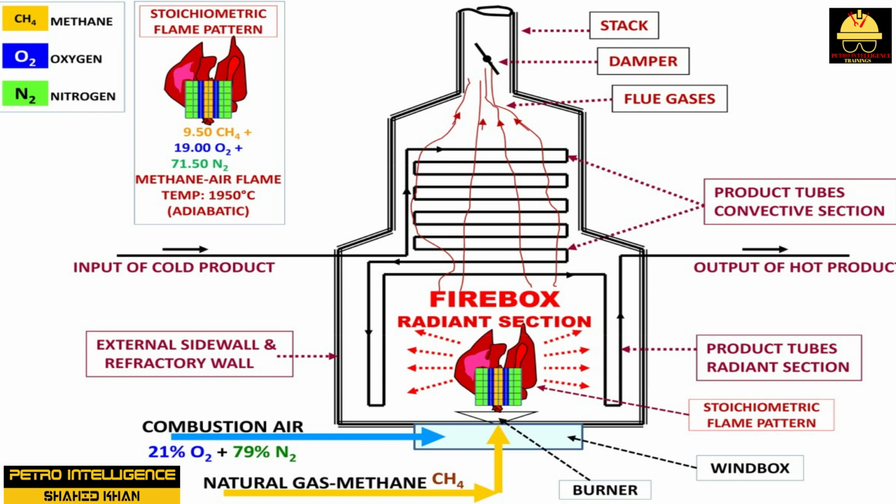Modern burner design consumes 100% of the fuel with a nominal excess of 10 to 15% oxygen. Excess oxygen in the furnace is carefully controlled as it enters the secondary and primary registers. This control takes place as the fuel and primary air mix at the burner and is enhanced by adjustments on the secondary air registers mounted on the outside of the burner. An oxygen monitor carefully tracks the composition of the hot combustion gases. Adjustments to the airflow rate are made at the burners and the stack damper.